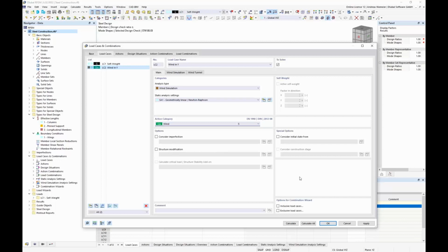So you get a lot of options, and the question could arise, is this really needed for a CFD calculation? Why do I have to specify here if I want to calculate according to second order or large deformation? I agree, at first point of view it's questionable, but you have to know that wind simulation is a two-stage calculation process.